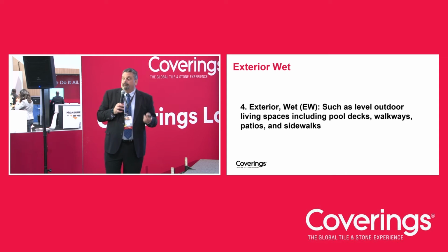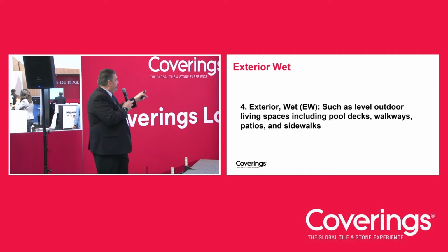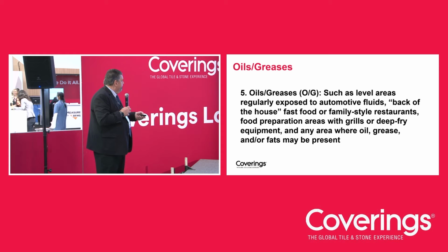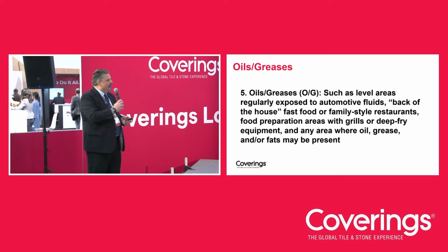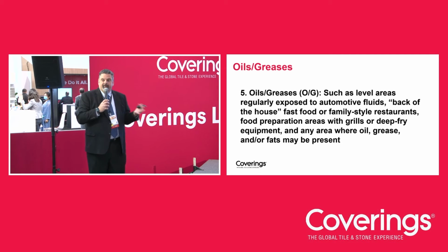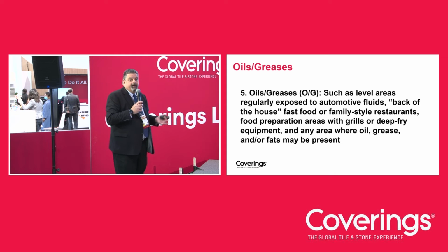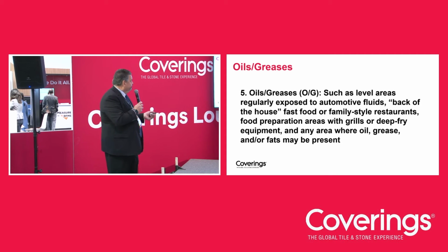As you walk around the show floor today, you're going to see a lot of the new 2cm, the really thick tiles that are designed to be outside pavers essentially. All of those should have a rating that's at least exterior wet. And then oils and greases, this is near and dear to my heart as a quarry tile supplier. These are more back of the house kind of applications, things where you do have a deep fryer, for instance, or even if you're working on cars and you have transmission fluid or oil on the floor.